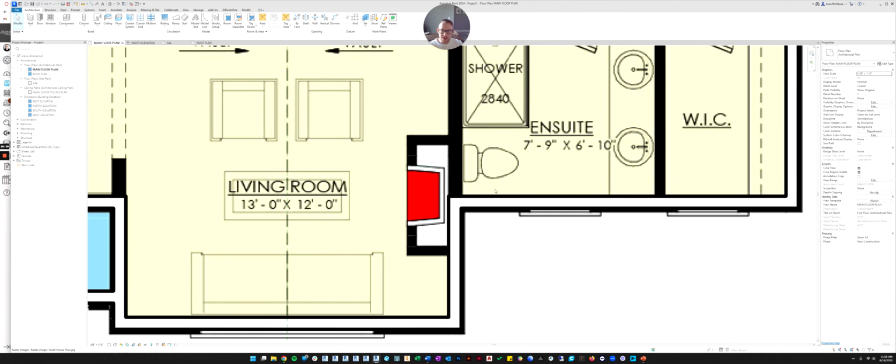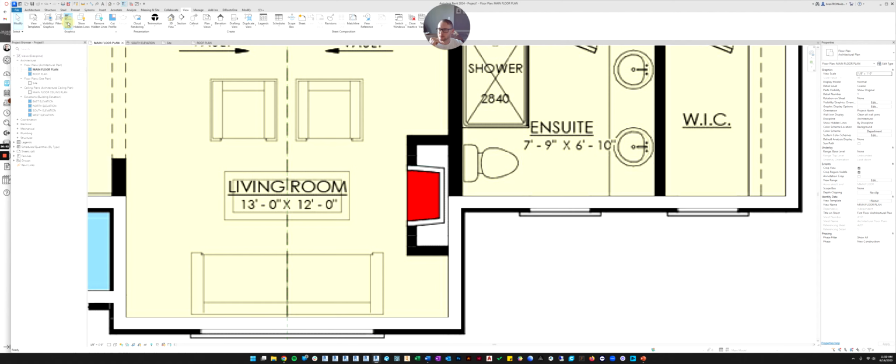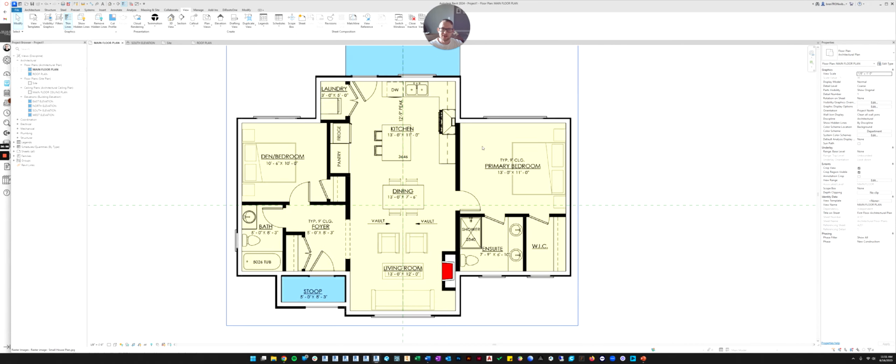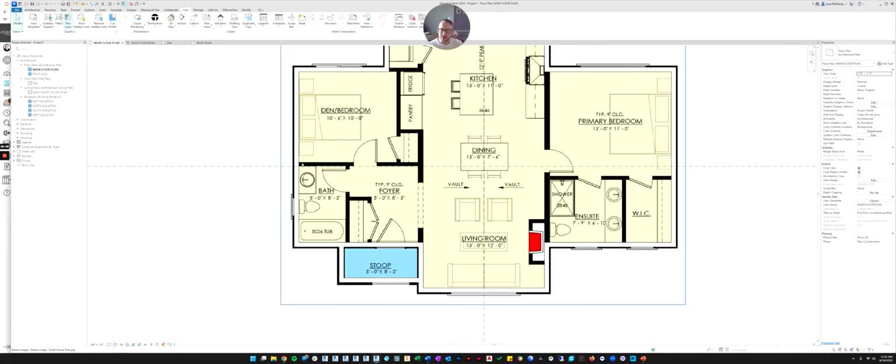Another thing I'm going to do right now is I'm going to go back to my Modify tab. Is that where it is? Oh no, the View tab. If I go to the View tab, I'm going to turn thick lines off because I find them really distracting. When I'm drawing, I like thin lines so I can see exactly what I'm selecting.